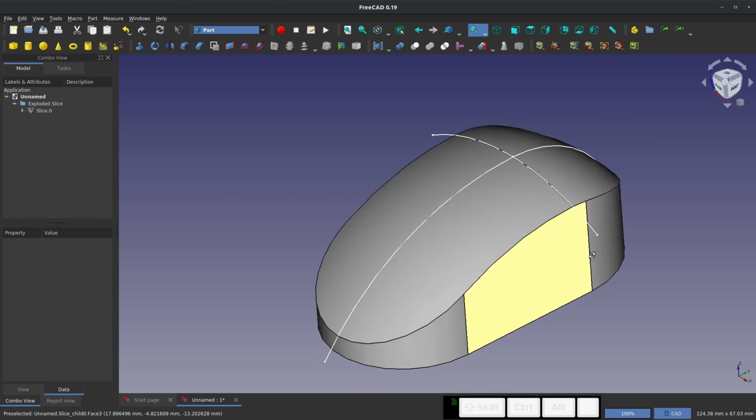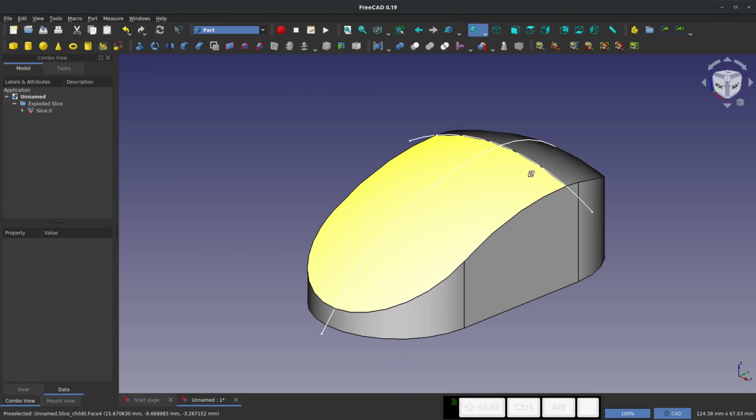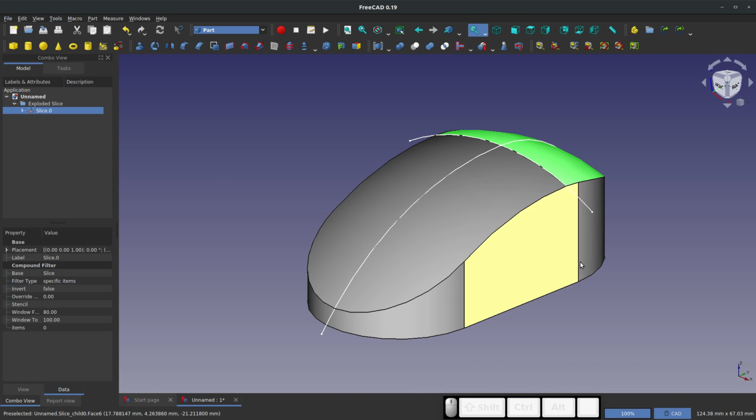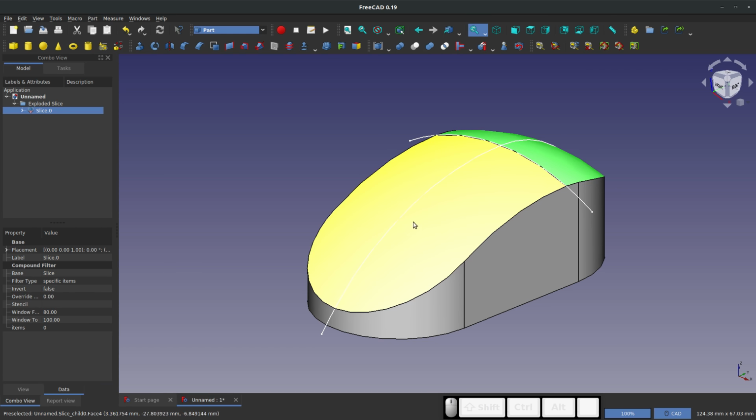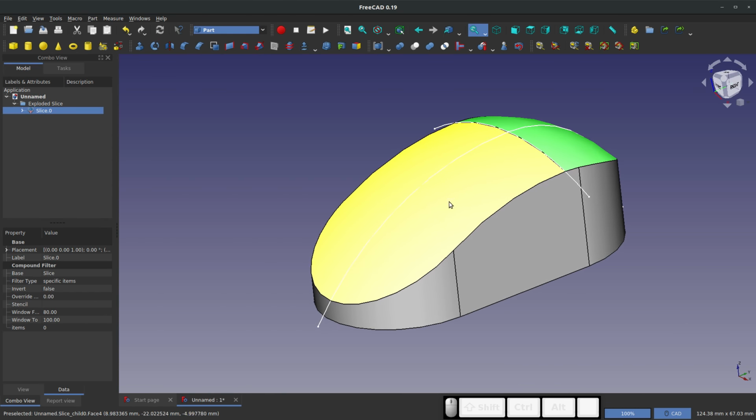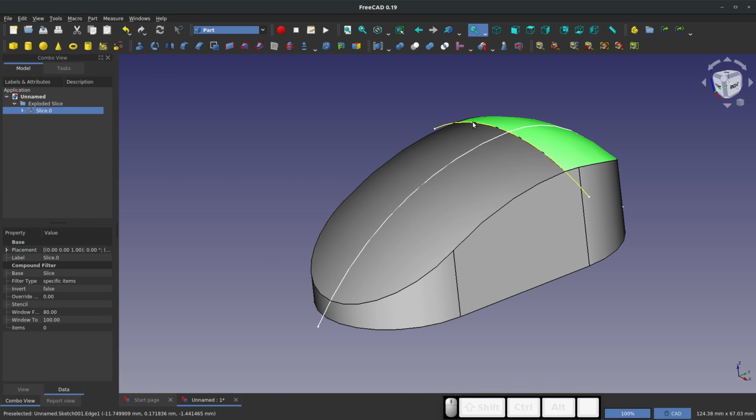So that is one way that you can use surfaces, right? You can make one surface at a time and apply that to a solid rather than having to try to loft or sweep something like this, which would be so difficult. You could do it. You could make it work, but you'd have to do it in multiple operations, where this was kind of clean.